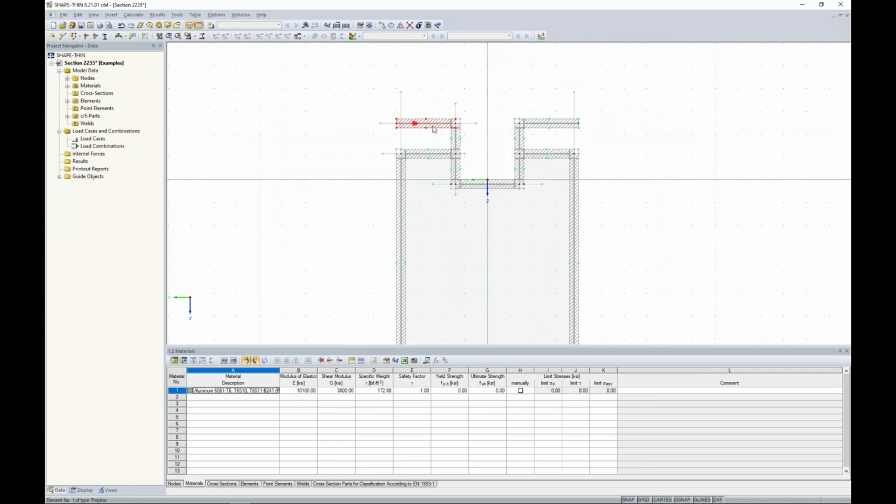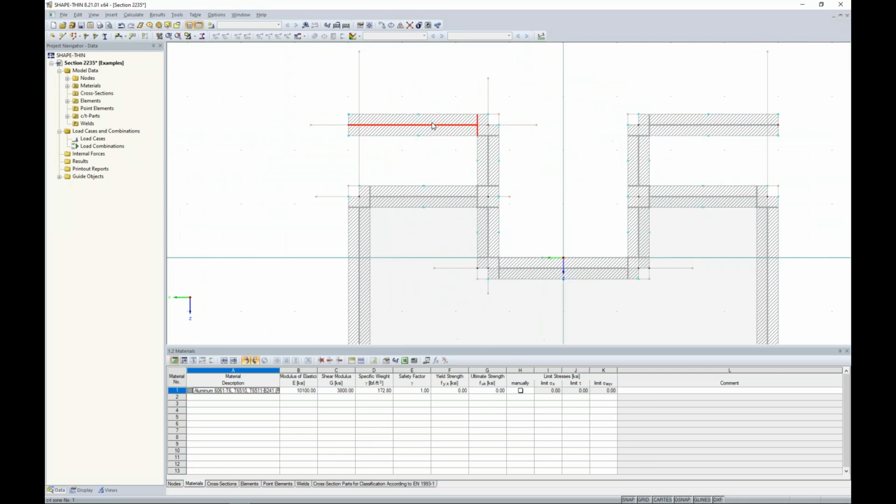Now, you'll see these symbols at each element, and these are the width to thickness symbols, those C over T parts. So this is what's recognizing width to thickness, but even more so, you'll notice that at these closed ends we have what looks like a T symbol, but at the open ends we don't have that same symbol. So this again is important for aluminum design to tell the program how the edges are supported.